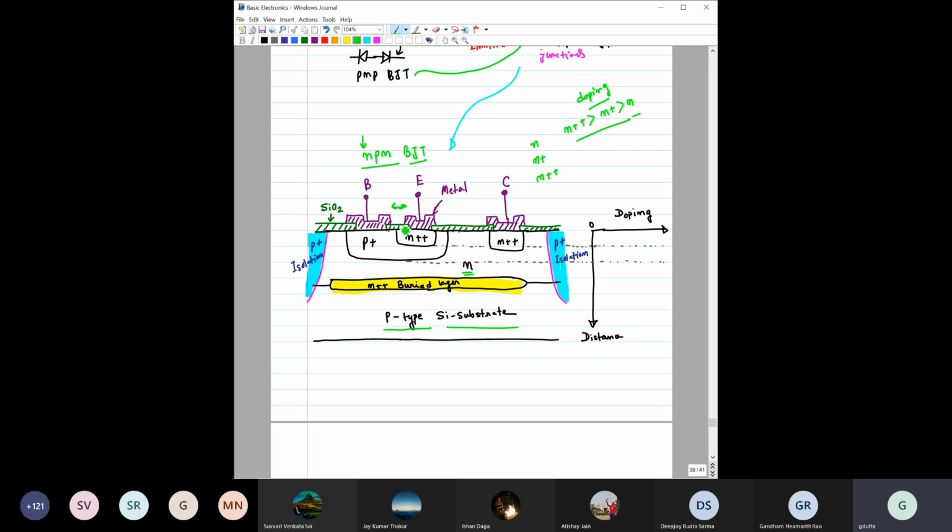So you can see that physically they are separated, and some part of the contact is also staying on top of the silicon dioxide, to prevent shorting, right? If the silicon dioxide was not there, and this metal shorted this side and that side, then what would happen? Basically the P plus and N would be shorted by this metal, right? So to prevent that, we use silicon dioxide, keep some part of it here, and only in between this region we open and create a contact with the P plus region. While fabrication, these types of safeguards are used.